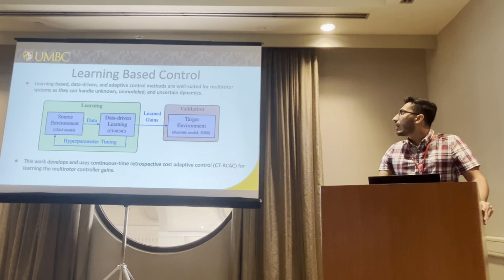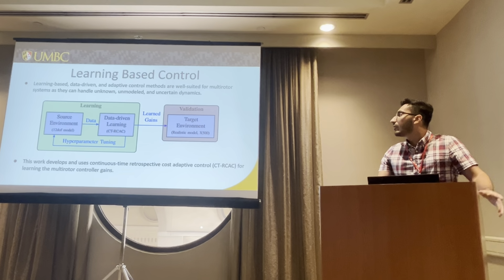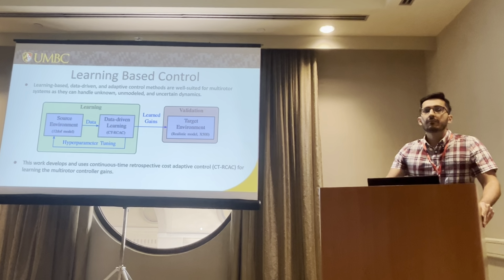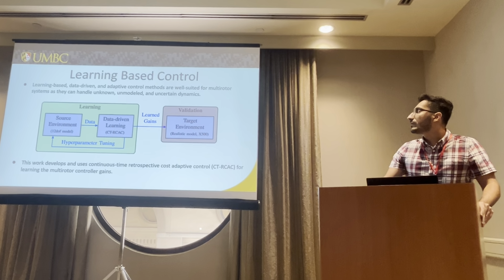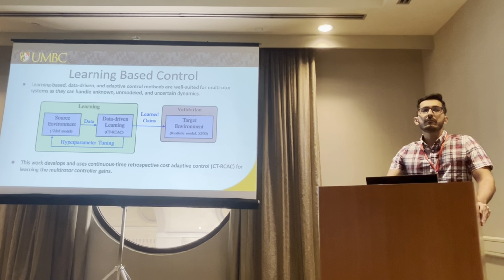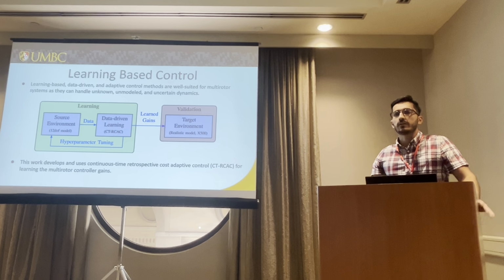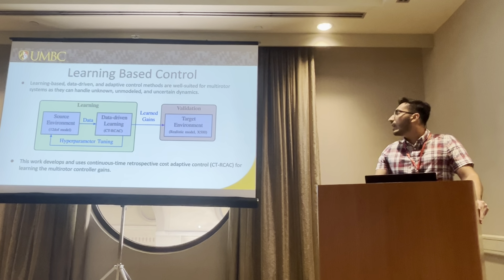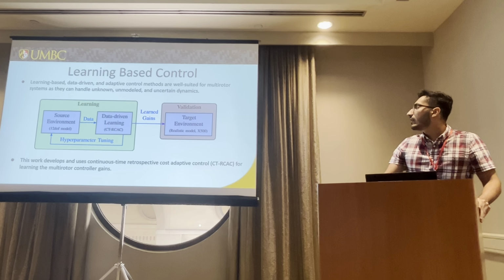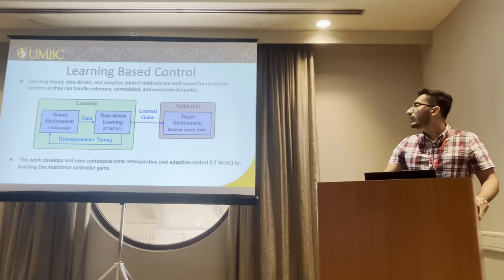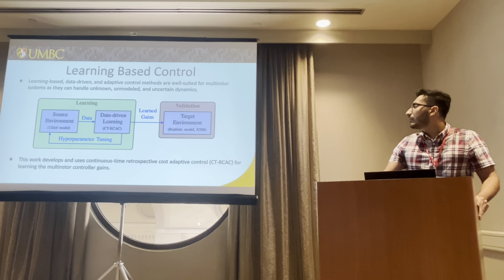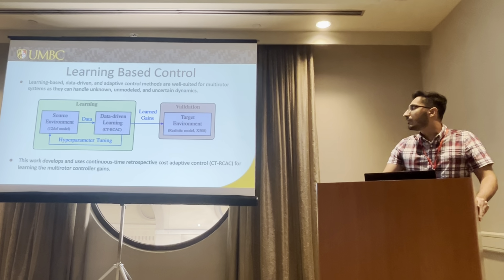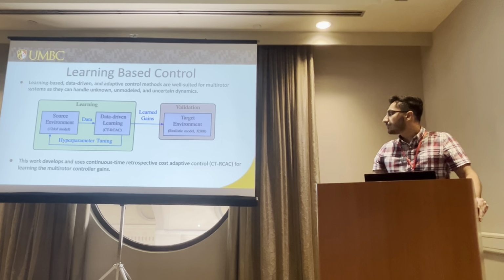We use a validation environment, which is a realistic model provided by MATLAB. It enables us to do hardware-in-the-loop and software-in-the-loop validations with Pixhawk flight controllers. And finally, we transfer the learned controller to the Holybro X500 and perform outdoor flights like this.